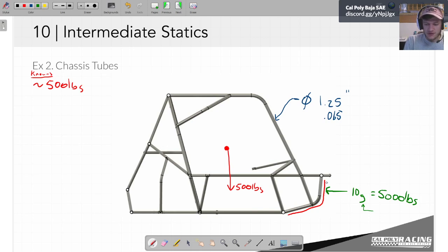So the front skid plate here is designed to take an impact load of 5,000 pounds, and I think that's a good place to evaluate my chassis at, right? If the chassis can withstand 5,000 pounds, then that means the skid plate will break before the chassis breaks, and the driver should be safe because we've already accounted for some safety factor in here, where this is already potentially stronger. This is our designed failure mode for a front impact versus the rest of our system.